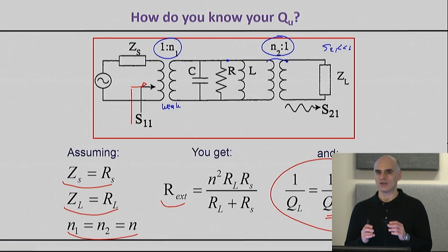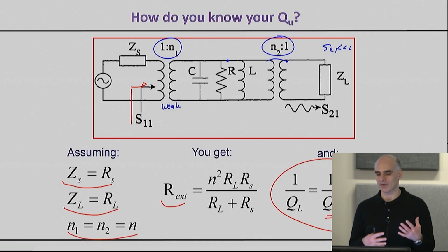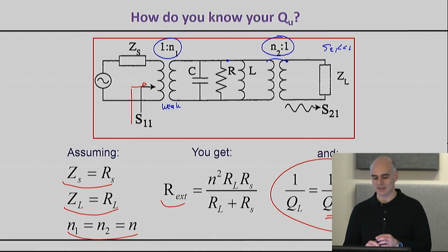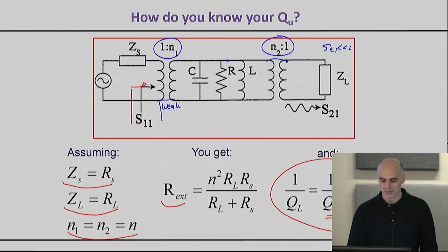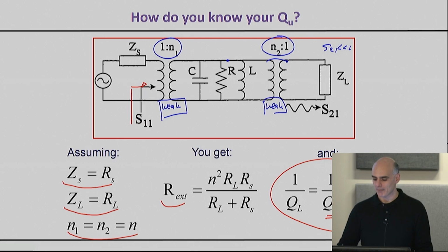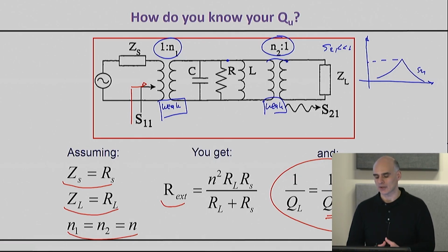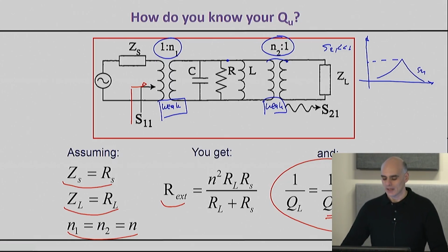So even though for your actual filter designs you know the coupling sections, because they're coming from your Chebyshev and the J equations and everything else we have discussed, when you make a circuitry to measure the quality factor of your resonators, you must make the circuit such that this is weakly coupled.